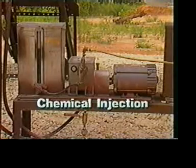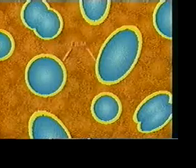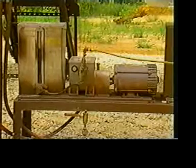Another form of treatment is chemical injection. Emulsion-breaking chemicals are injected into the well stream ahead of the heater treater. Chemicals react with the film that surrounds the water droplets. This reaction destroys or neutralizes the film and allows the droplets to combine or coalesce with each other and separate from the oil. There must be sufficient agitation to allow the chemical to come in contact with each water droplet.